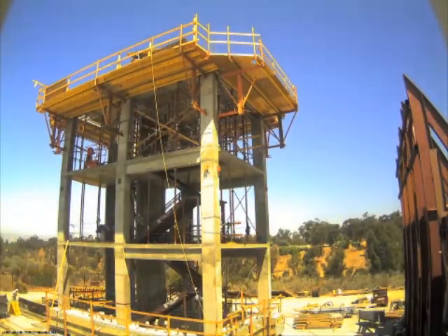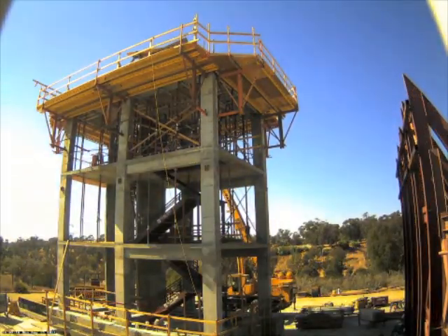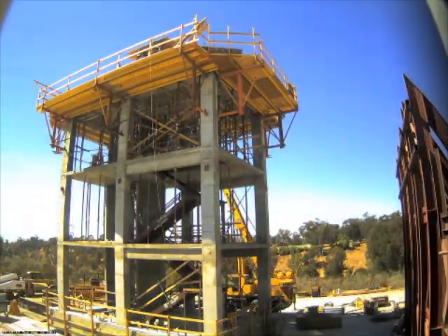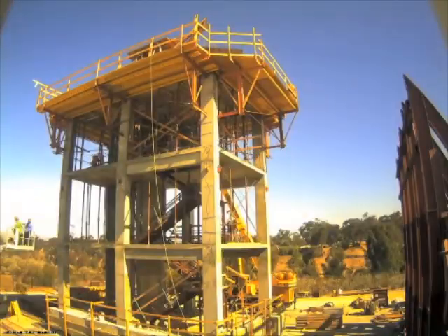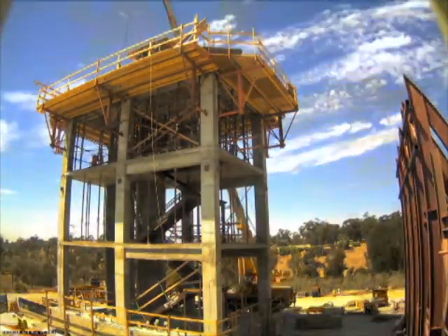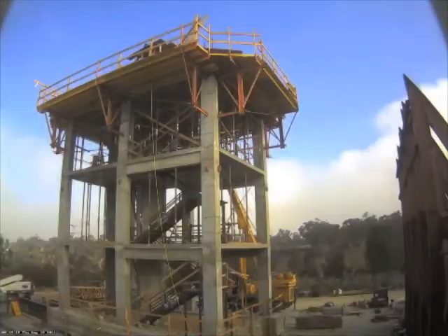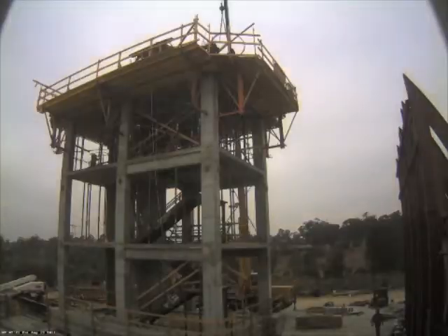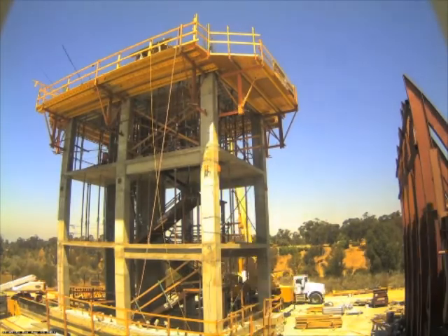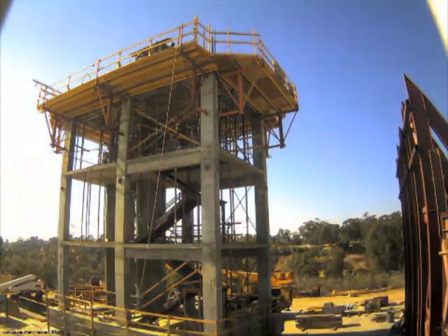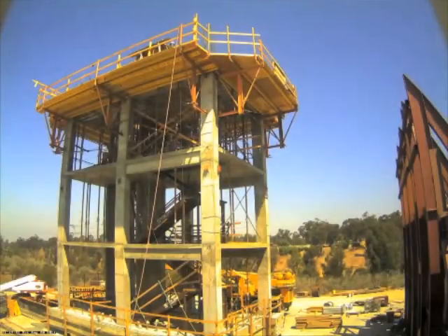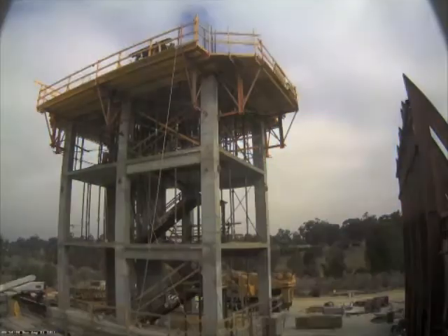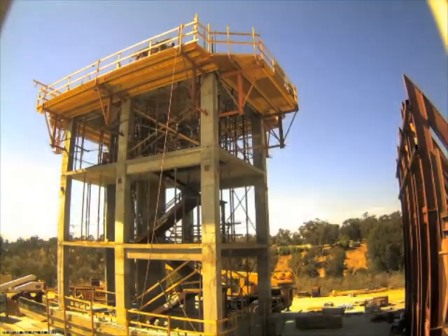There are 2 types of system formwork, jump form and slip form. Slip form usually makes use of its own hydraulic power to lift itself up against previously completed floors and is suited for tall structures where no change in formwork is required. On the other hand, jump form requires a crane to lift it up for each cycle. In this project, jump form was used for the upper floors. Once the second floor was completed, the system formwork was raised for construction of the third floor, where the columns and shear walls were installed. This process was repeated for each subsequent floor.